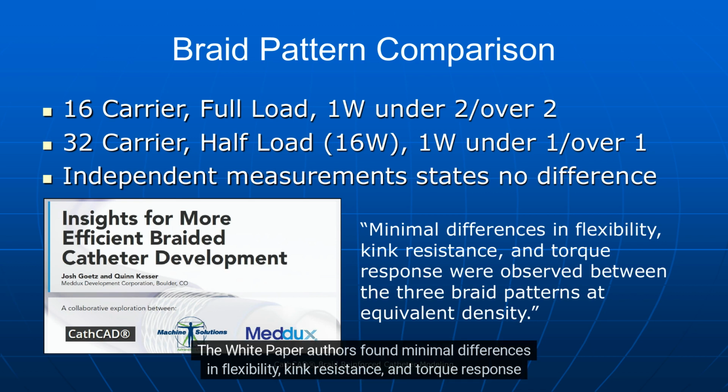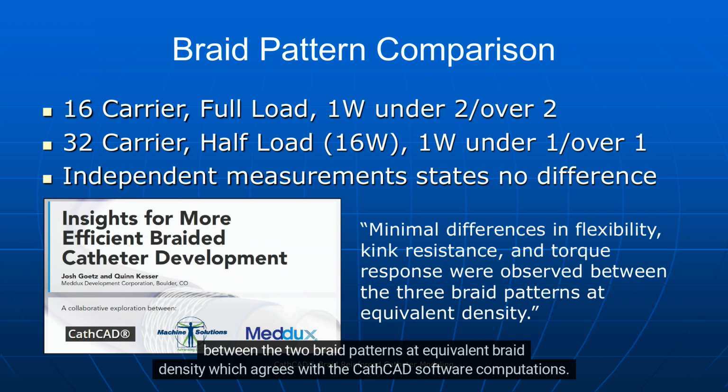The white paper authors found minimal differences in flexibility, kink resistance, and torque response between the 2 braid patterns at equivalent braid density, which agrees with the CathCAD software computations.